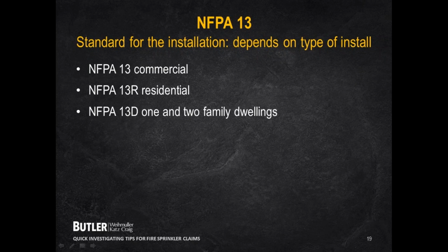I know in Florida, any 3-story building that is a residence must have a fire sprinkler system in it now. Condominiums, townhomes, regular standalone residential properties, those are the current codes in Florida. So you will see fire sprinkler systems in residential properties as well.